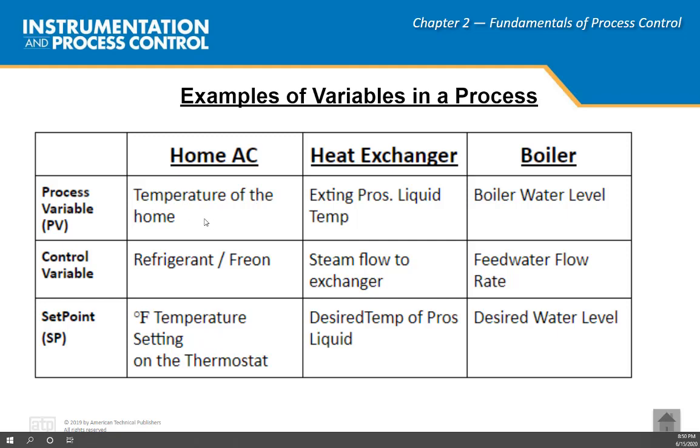Cold air of an AC system can only be 20 degrees cooler than the room air. So when you get in your car in the summer and it's about 160 degrees in there, your air conditioner is not going to blow out 60 degree air. It's only going to blow out 20 degree cooler than room temperature air. But as the temperature of the car cools down, the temperature of the air blowing out of the vents cools down as well.